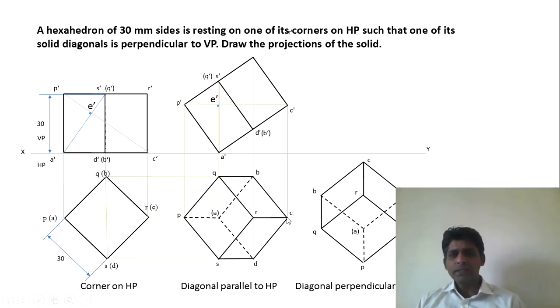Then you can measure CB. Observe that CB and CD are of same length. So measure CB on the compass, and from C you mark B, draw an arc here. At the same time you can mark arc D also because they are of same length. Then you will observe that RQ and RS will be of same length. So from R you can mark another arc here, and from R you can mark another arc representing this particular point S.